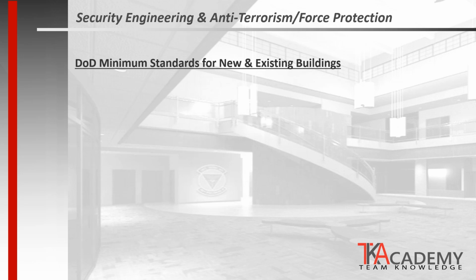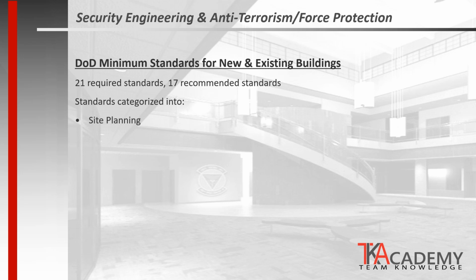The Department of Defense led the way in developing anti-terrorism force protection minimum standards for both new and existing buildings. Currently, there are 21 required standards. There are also 17 recommended standards. The standards are multidisciplined and can be categorized into site planning, structural design, architectural design, and mechanical electrical design.